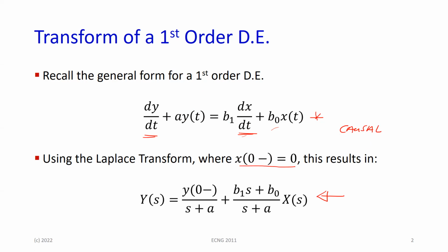We said that depending on what you're dealing with, sometimes you force the initial conditions to be 0, but it isn't always the case. And we know that circuits, for instance, that have capacitive or inductive elements in them hold energy. They will hold a voltage, they will hold a magnetic charge. And at the time when you do something to it, unless you took an active role in making sure that the inductors were discharged, that the magnetic field was discharged in the inductor, so it doesn't have anything to send back to the circuit, or that the capacitor voltage was set to 0, then you have to assume that there's some sort of initial condition around.